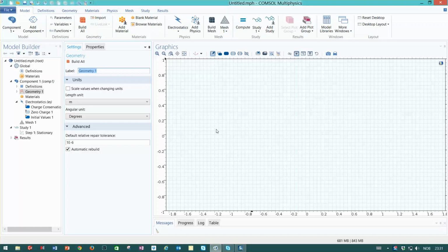I will in this tutorial assume that you now have an understanding that we need a refined mesh for some time, particularly if we have a solution that is very, very intense, or the solution varies a lot on a corner or a part of the problem, so that we need to do a more accurate analysis there.